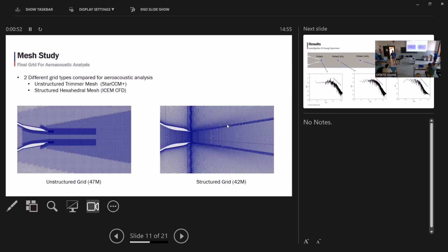So the unstructured model is 1. And in the unstructured grid, you don't have high aspect ratio cells. Basically, you want to resolve part of the spectrum, and if you have high aspect ratio cells in the region, that hurts the resolution, especially when the aspect ratio is even higher than 1. You can use the cube root of the volume, or you can use the highest length in the element, and it never works perfectly with the higher aspect ratio cells. Maybe it's not that the structured approach is bad, it's just that you need to focus on having a good aspect ratio over, for example, the whole region.